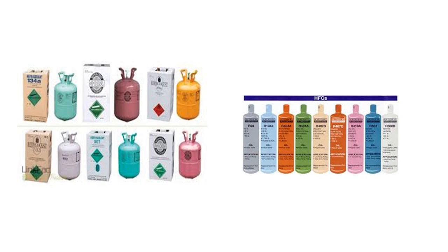Now that we have discussed the types and components of AC and refrigeration systems, let's talk briefly about the refrigerants that circulate through them. There are many different refrigerants available today. Different systems will use the refrigerant that best suits its needs. An example of this is a freezer will use a different refrigerant than an air conditioner due to the vast difference in their conditioned space temperatures. Refrigerants are designed to have a very low boiling point temperature, be non-toxic, and non-flammable. There are some dangers and laws regarding the use of refrigerants that will be discussed in depth in other courses.